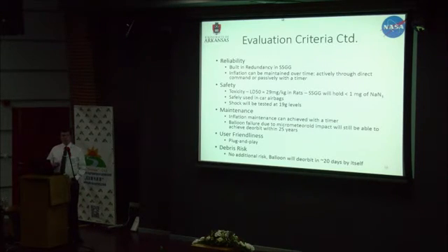Reliability. The reliability comes from the built-in redundancy in the solid-state gas generator. It'll likely take only a few gas wells to inflate a balloon. The volume of, say, 10 micrograms of gas, which is what our prototypes were producing, would create a sphere of about 1.3 meters in diameter at 200 kilometers altitude. You're going to need more gas than that to inflate the balloon.